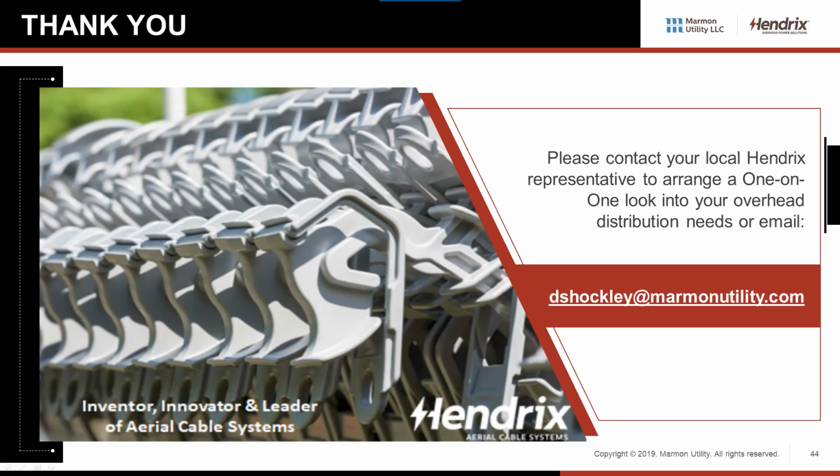We've also looked in the past at having almost an add-on to our spacer that will support a separate piece of fiber optic, but I'm not sure where that project is at. But yes, in the past, we've used OPGW with the spacer cable system, and it's been a good solution. We're happy to work with another manufacturer for that messenger, because obviously we can get it, but we don't manufacture it in-house.